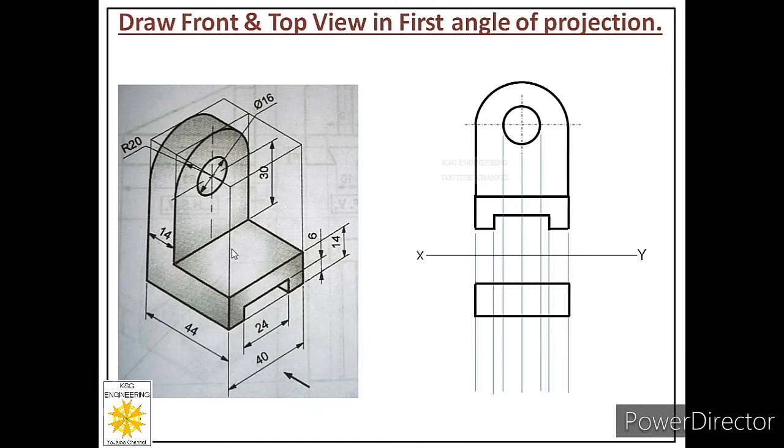So after that we have to plot the second visible face, that is this parallel face. So in order to plot this face, we have to first see how many points are there, and we have to pick one point and we have to locate that point with respect to the previous face drawn by us. So let us pick this point of the second face. Now you can see this point is exactly below this point. That point is over here. So from this point we will sketch the width of the second face.